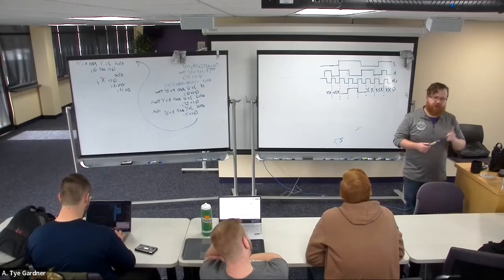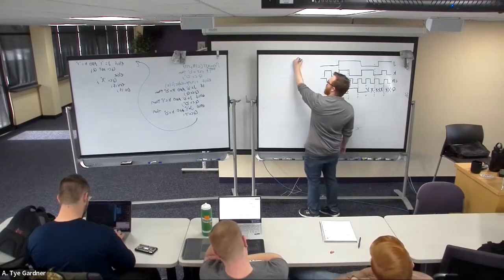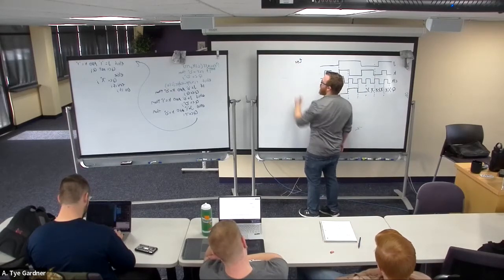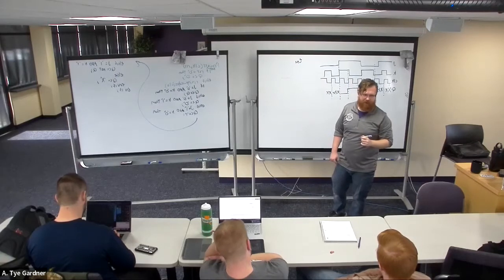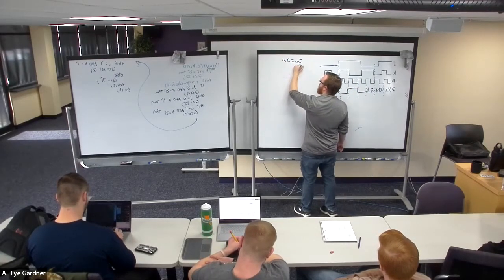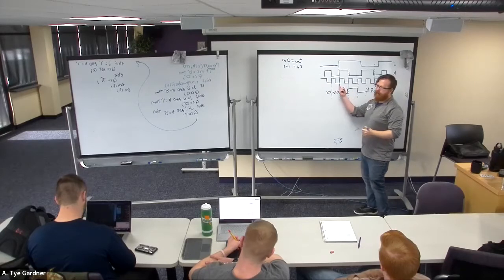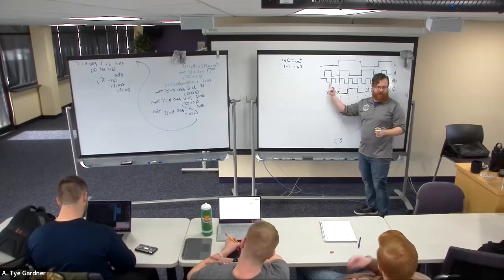And in fact, in general, when I give you questions, I'm going to define terms, if you recall these, like TSU, setup time. I'll say something like this is 2 nanoseconds, and there's a T hold, and this is equal to 1 nanosecond. Then I'll give you these timing diagrams, and they'll have timelines across them, like these dashed lines that I'm drawing on my hand.